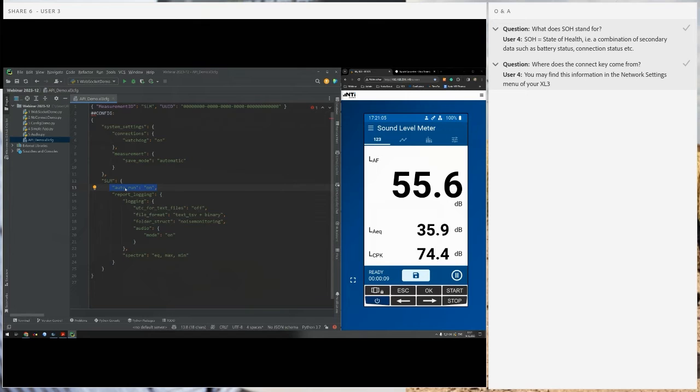And what we have seen in the past with our noise card system and with other customers, sometimes customers forget to press start again. And with auto run on, the instrument will automatically restart the measurement 60 seconds after you have stopped operating the system manually. And there are many other situations where this setting just takes care that the XL3 always does its best to record data.